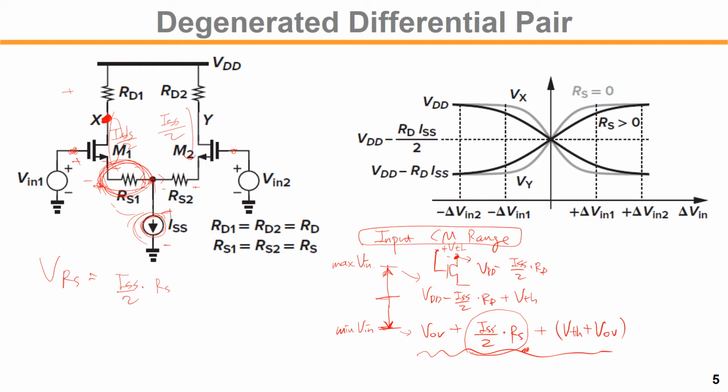What about the output range? Let's find out the output range. The maximum would be VDD, and the lowest peak, assuming gain is high, would be the input common mode Vin,CM minus VTH, because of the higher input common mode range, right?